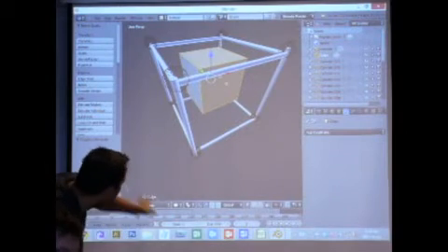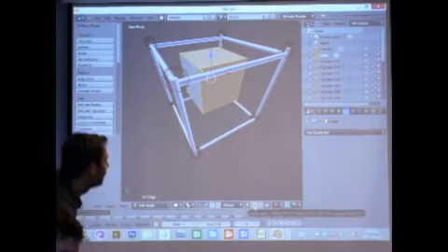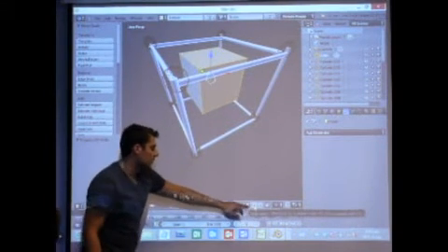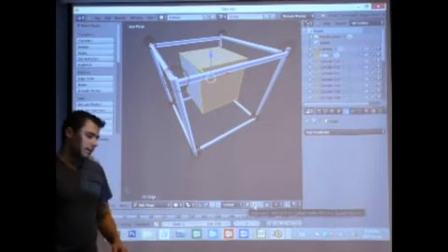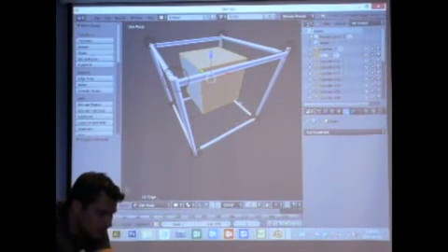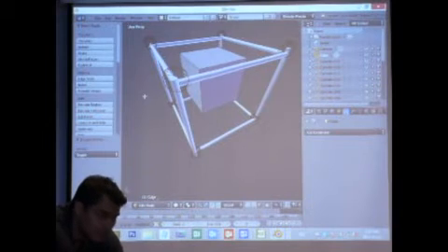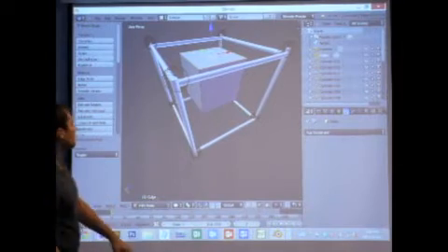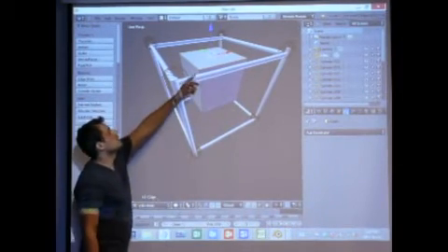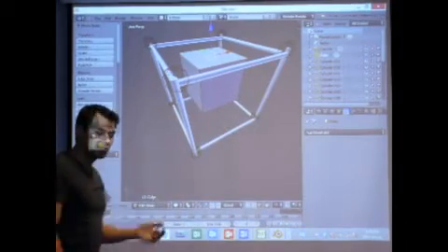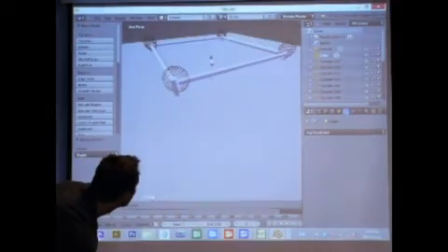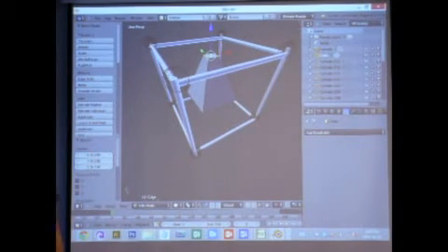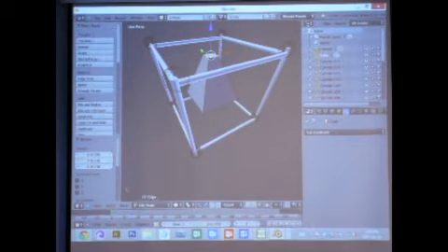Right now all the faces are selected. Down here you have these three options: face selection, edge selection, and vertex selection. We can change this to make sure it's face selection. A would deselect everything. Because we're in face selection mode, I can just right click on the top and it will select the top face. And you can scale that independently of the actual object itself. So you create this easier object.